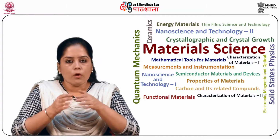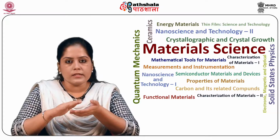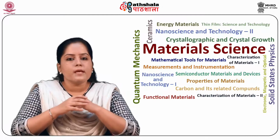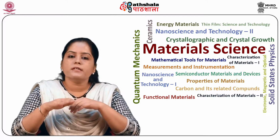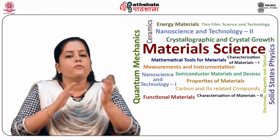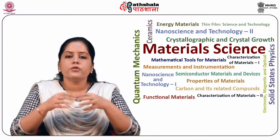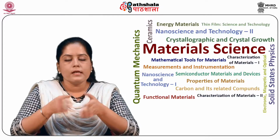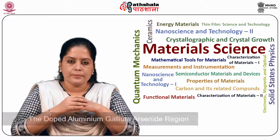Now let us discuss the fabrication of MODFET. While fabricating MODFET, firstly an intrinsic layer of gallium arsenide of 1 micron thick is deposited on the semi-insulating gallium arsenide layer. After this, a very thin layer of aluminium gallium arsenide of 30 to 60 angstroms thick is deposited in order to introduce the separation between the heterojunction interface and the doped aluminium gallium arsenide region.